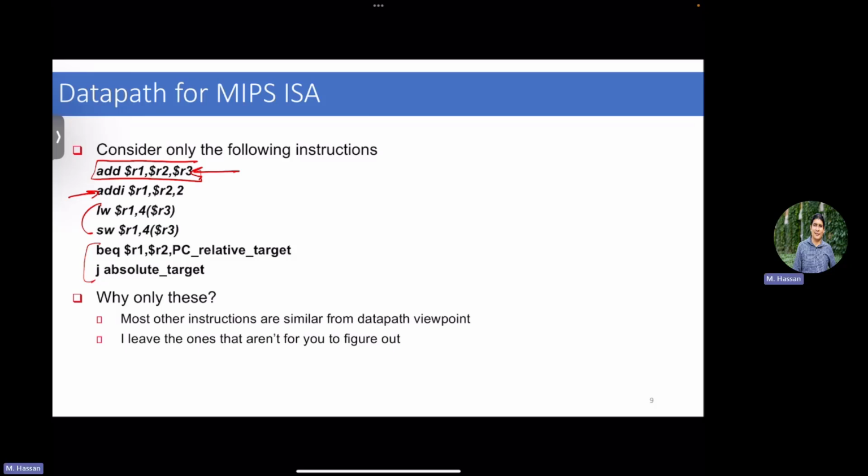Good. So before delving faster, I keep saying there are function units. You got introduced to ALUs in your 2DI, but what is a register file? I think you might have interacted with register files in 3DQ, for those that took 3DQ. Simply, a register file is a bunch of registers. You can look into them logically as one set. Sometimes they're implemented as real registers, sometimes they're implemented in FPGAs as block RAMs, right? But you can think of it as a simple memory